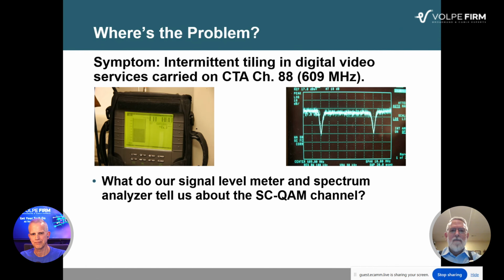Cool. So let's do a hypothetical out in the field, and this is one that may be all too familiar to many people. So let's say there's a symptom. Customer calls up. They've complained that there's intermittent tiling in some of their digital video channels, and you do a little check and you check your list and say, oh, all those digital video channels or signals that they've got intermittent tiling on are all carried in the same CTA channel. In this case, we'll say channel 88. That's a center frequency of 609 megahertz.